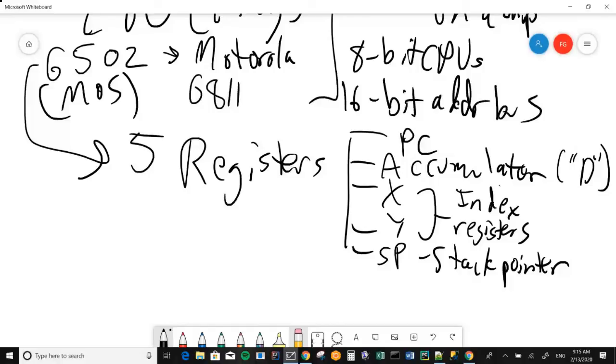Yes? So there was, again, a register on the graphics card, memory mapped, where you specified what color you wanted when you were rendering something. So it could be as simple as, if I'm plotting a pixel, I want it to be a certain color, I would set that color register to specify the color, and then I would tell it to plot the pixel, and that pixel would appear in that color.